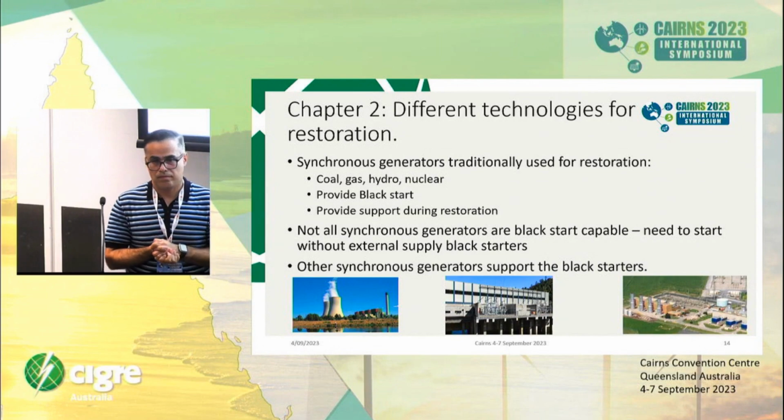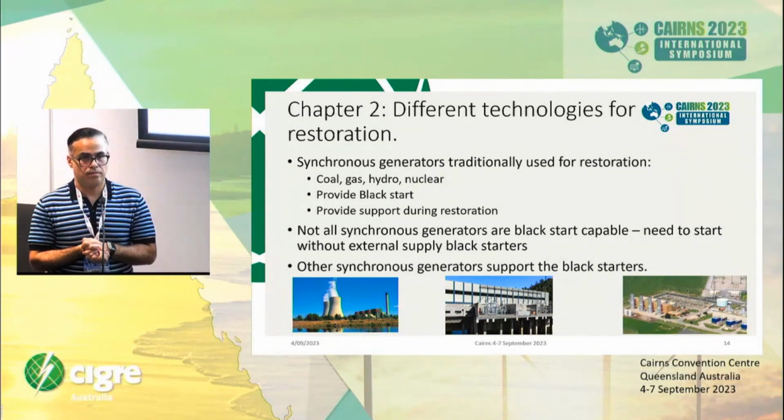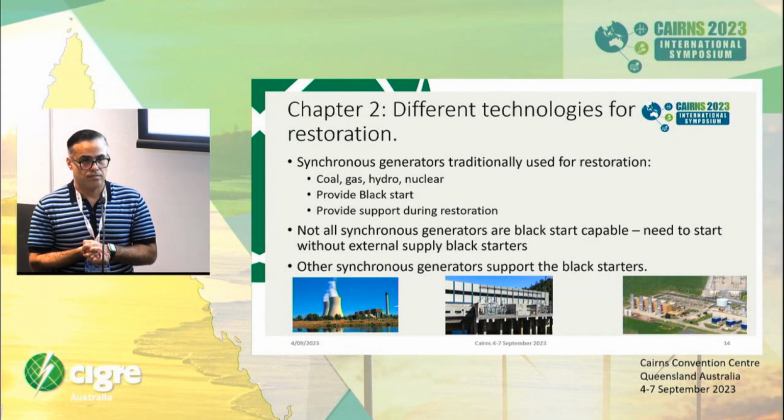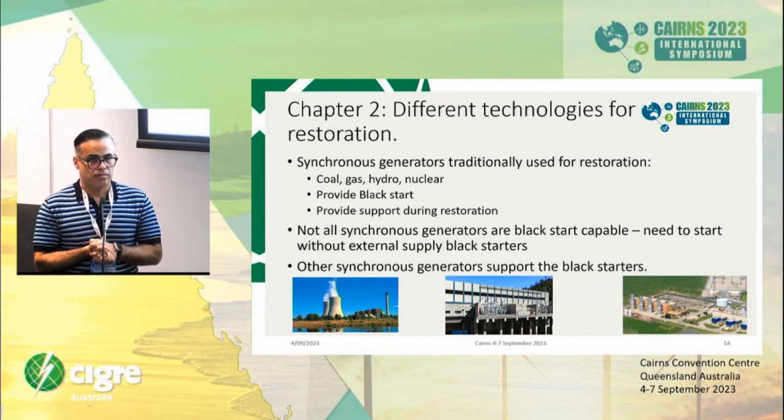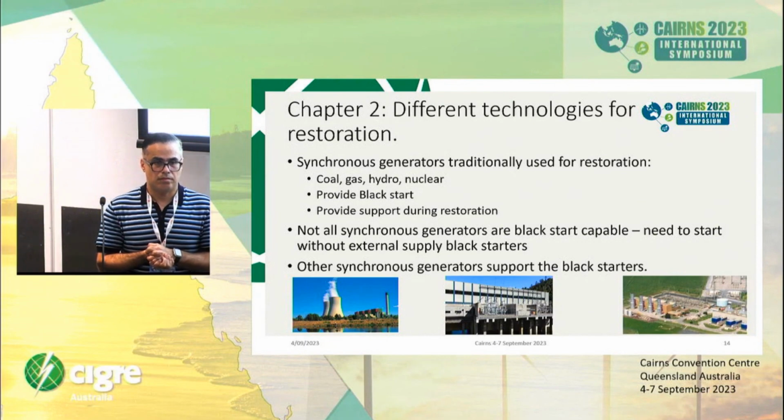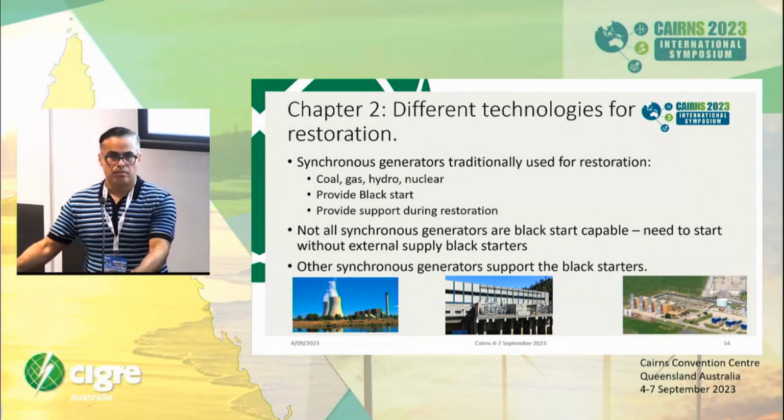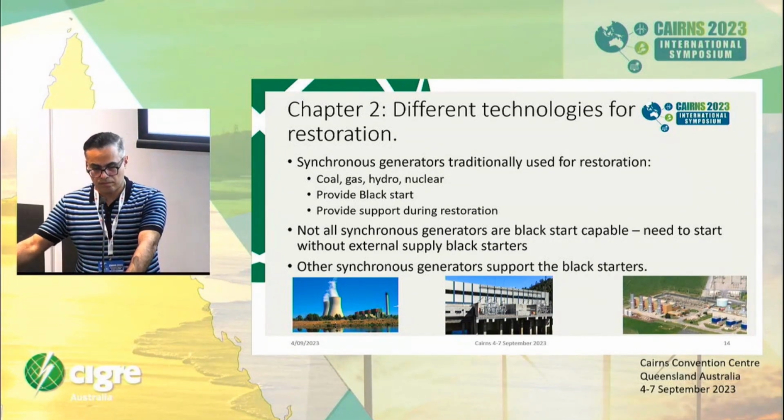Yeah, thank you, Ahmed, PwC, Northern Territory. I'm just interested in what you just mentioned as well about, so you are considering the inverter-based technology more regarding black starting. You're not considering restarting the system, knowing that the main challenge that we have, especially in a small network like the Northern Territory, is the system restart through creating corridors and energizing transformers and rush currents, and obviously putting stabilizing load on the system.